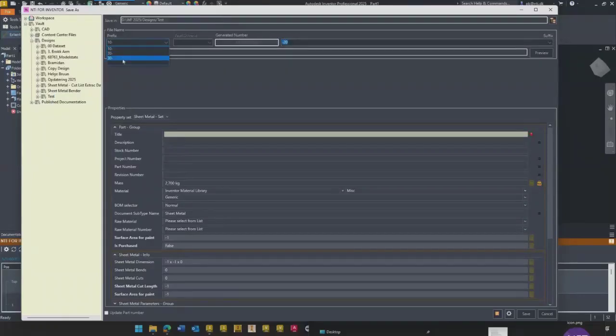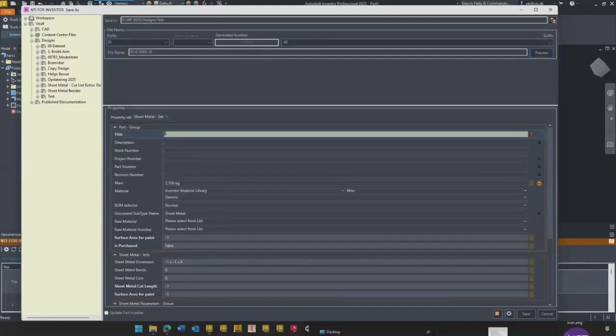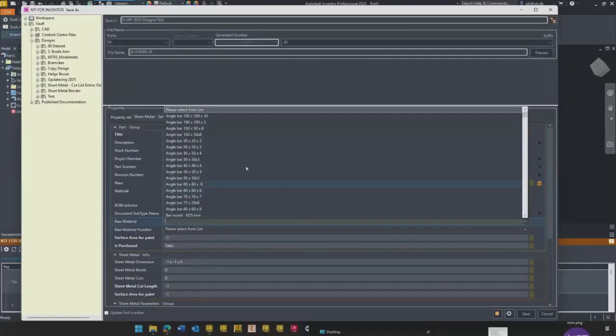You have a prefix, and you have a suffix. You don't have to use them, but you can, and you can get a preview, and we'll just draw a new number from the rule I have set up. In this case, it's 6 characters, but it could be as many characters as you want. Again, my property editor is built into this number generator, so it will appear when you're saving your files, to remember to fill out different lists or different properties.